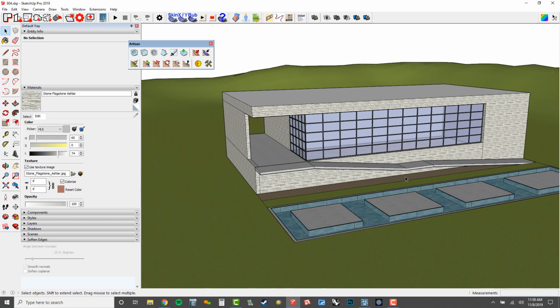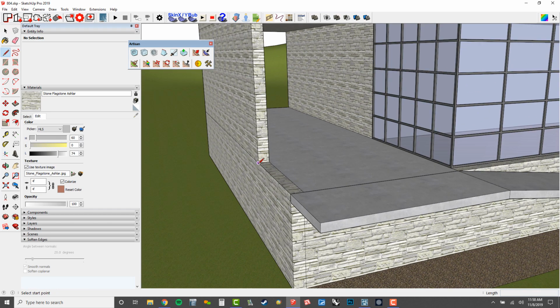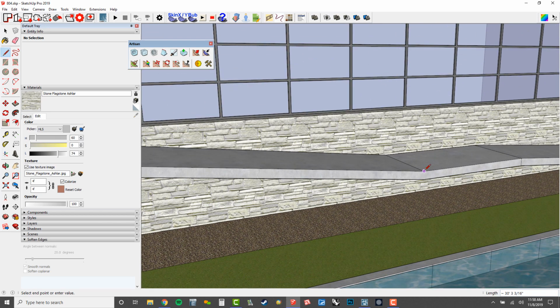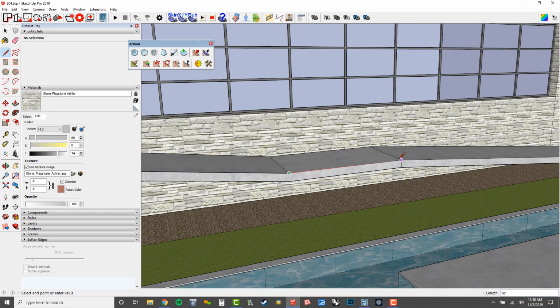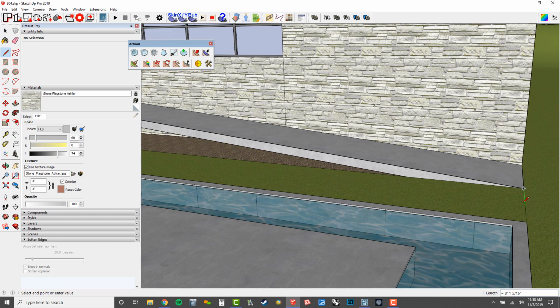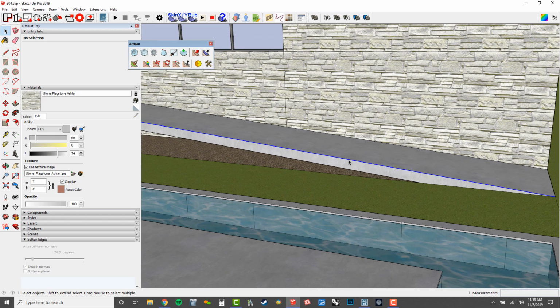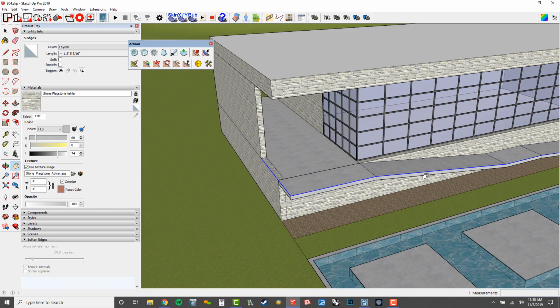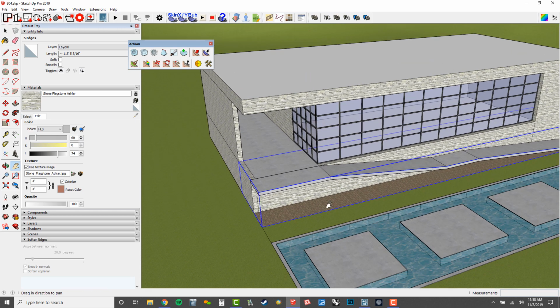All right. So the other thing I think that makes renderings really pop are railings. That's super important, and they're very, very difficult to model. So check this out. There's a plugin called Instant Railing. I just need to draw a path, and I'm just going to trace down this ramp like that, and get to the end here. All right, and then I'm going to use my select tool, and if I triple click it, you guys should be able to see that there's a blue highlight there, and I'm going to make that into a group.